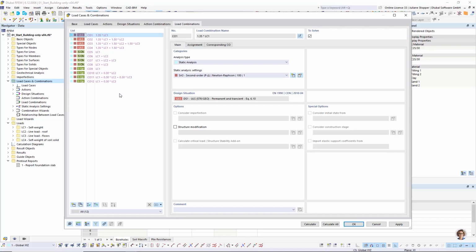So we have this here, the advanced half space method is called in RFEM 6, and in RFEM 6 this will be done for every load case you solve or for every load combination. So this is the default behavior. If you calculate any combination, it will just use the advanced half space method, and it will calculate for every load situation, for every combination, the corresponding foundation coefficients. Yeah, this is the behavior.